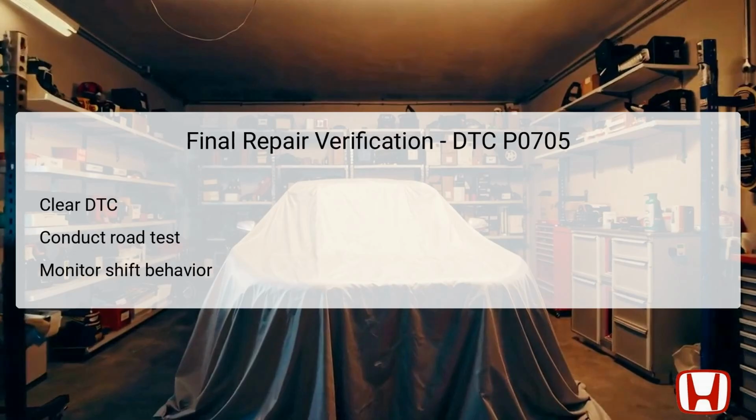After repairs have been made to address the issues with the transmission range switch or TCM, the next crucial stage is the final repair verification. First, the DTC needs to be cleared from the TCM using the HDS or an equivalent diagnostic tool. This step resets the system and stops any warning signals from obscuring the results of the next tests.